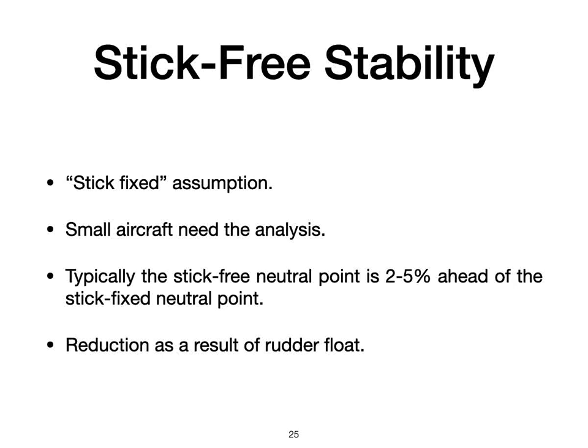Many smaller aircraft use purely manual or simply boosted control systems in which the air loads upon the control surfaces cause them to change deflection angle as the angles of attack and sideslip vary. Such a case requires a stick-free stability analysis.